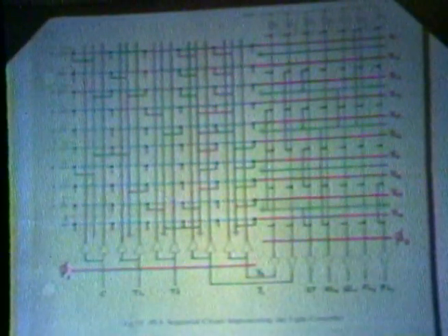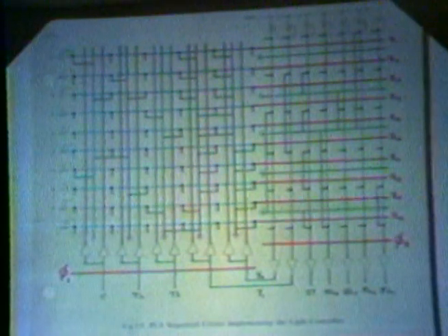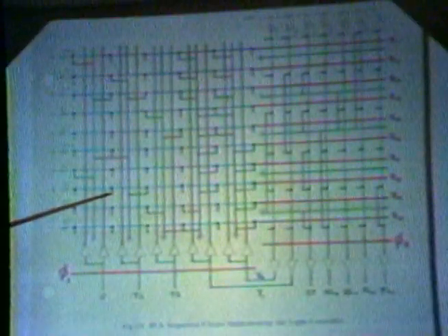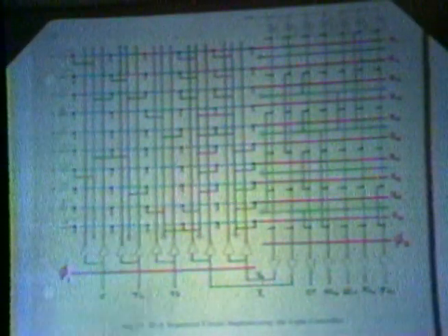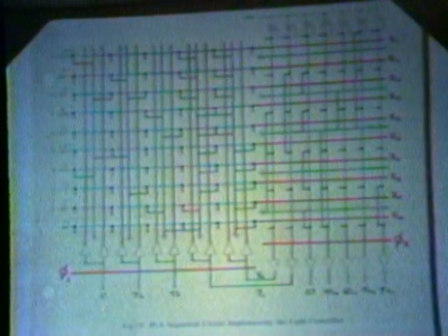Ted? Is it generally true that cells in PLAs are square because they have to match up on both dimensions? Absolutely. The cells in here are square for exactly that reason. That is that the cells in this array should be identical to the cells in this array, and they have to be turned at 90 degrees, and therefore to have the same pitch, they are constrained to be square. That's a good point.